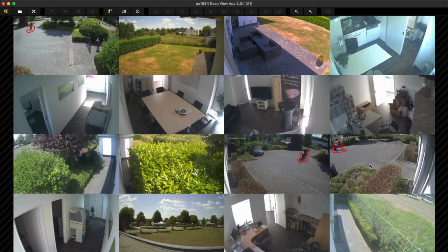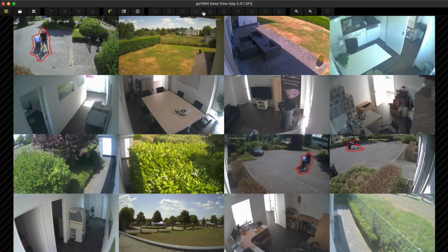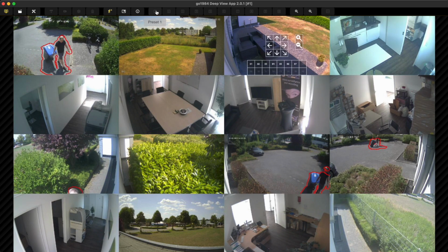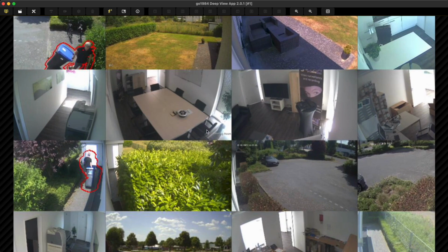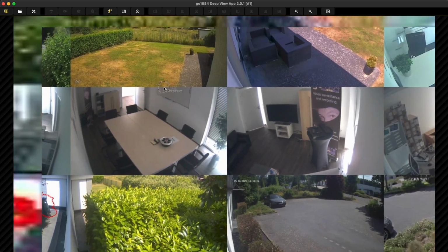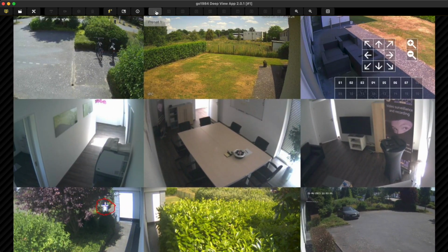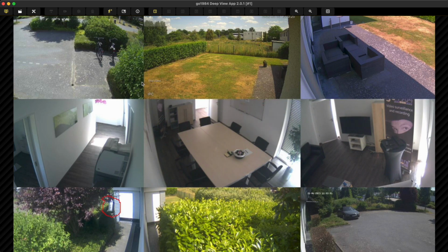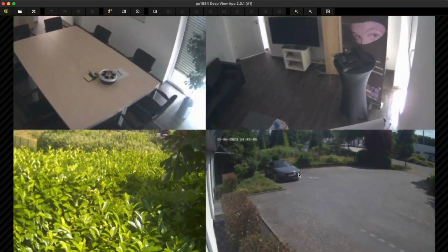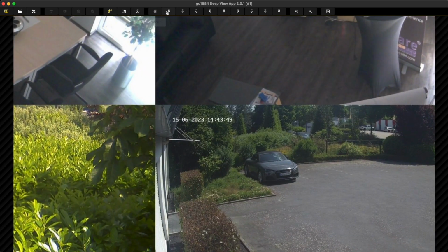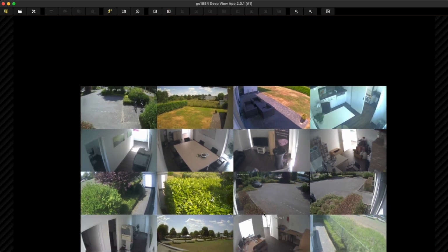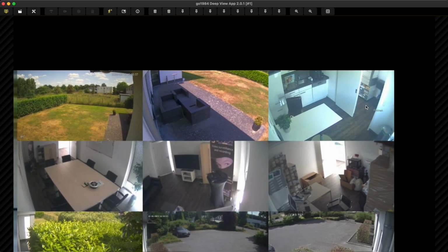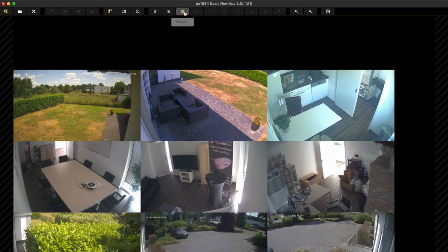You have 10 position buttons available to save view areas. Hold down the Alt key, or Option key for Mac, to identify available positions marked with a pin symbol. To save the current view area, simply click on an available position button. You can access the saved positions by clicking on them or by pressing the corresponding keys 0 to 9.